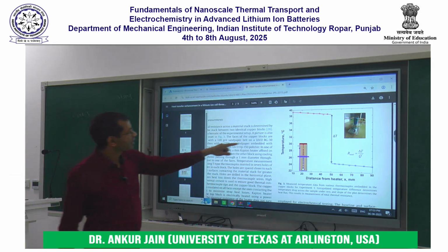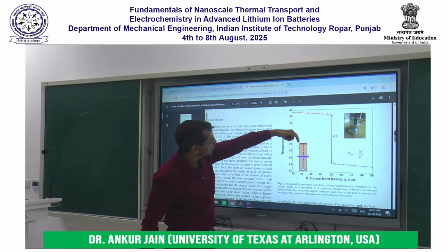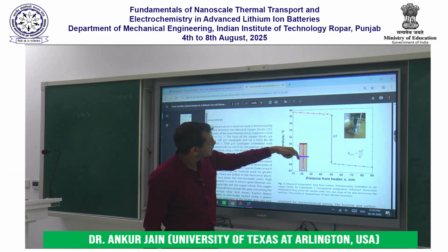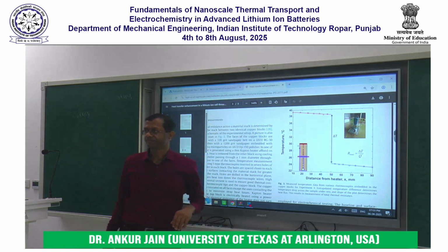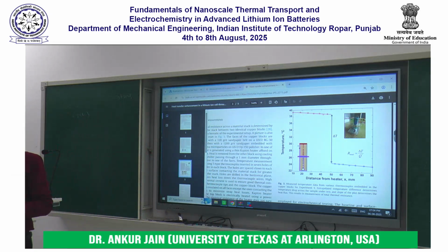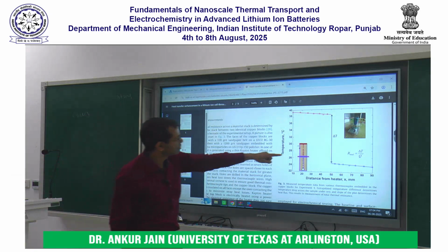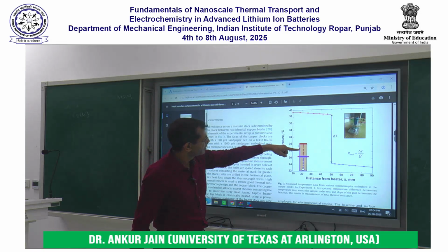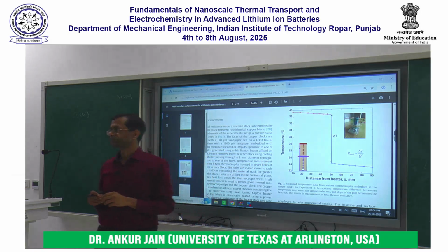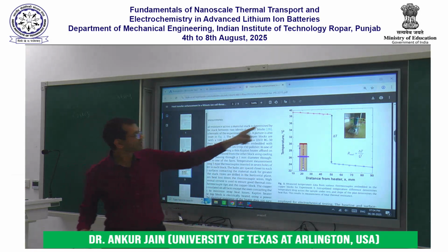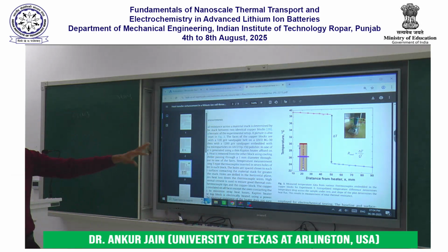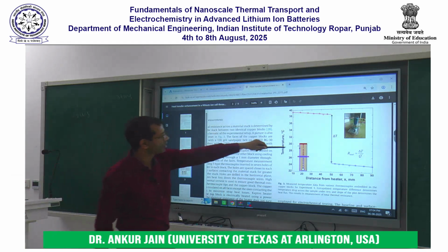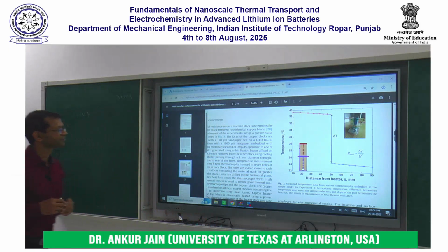I have heat entering this copper block from the top and heat leaving from the bottom, picked up by the cold water and taken away, right? During this time, this heat has to pass through the cathode material to jump from the top block to the bottom block, right? This is a typical temperature versus X plot based on the 15 or so thermocouples that we had. The red ones are in the top, the blue ones are in the bottom.